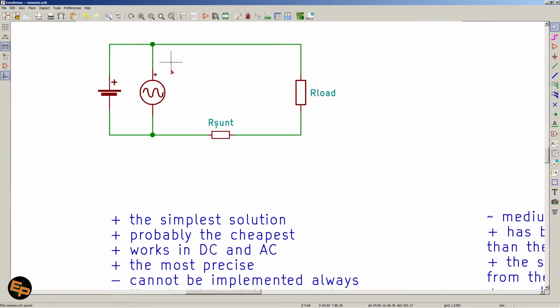So if the circuit that we're trying to measure is this one with the voltage sources and the load, and we put the shunt resistor in order to get its voltage, in order to feed it to another circuit that measures this current, we're going to be working with the potentials that exist in the first circuit.